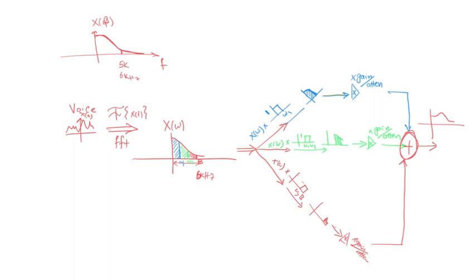Now this is the software part. What would you do in the hardware part? The last thing, just to remember, is you need to retrieve this signal back in time domain. So you have to bring it back as x of t. So you have to do an inverse FFT before taking your combined signal into the speaker of the computer. After combining them, they are still frequency domain signals. If you try to put that to the speaker, you will get some nonsense. You have to bring it back to time so that the speaker gives you an understandable audible voice, okay?